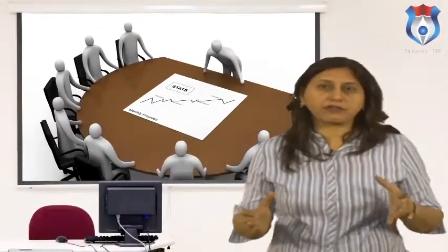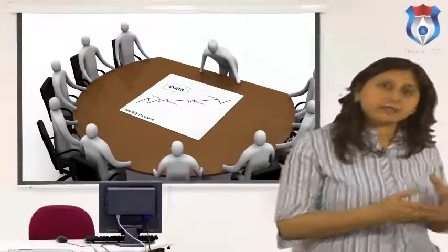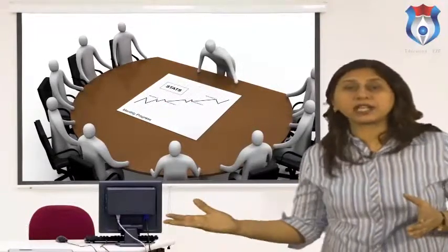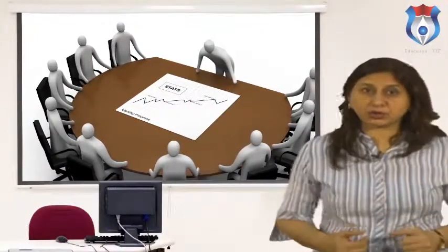Step 8. Establish experimental conditions for runs. Address the question of obtaining accurate information and the most information from each run. Determine if the system is stationary, where the performance measure does not change over time, or non-stationary, where the performance measure changes over time. Generally, in stationary systems, steady state behavior of the response variable is of interest. Ascertain whether a terminating or a non-terminating simulation run is appropriate.